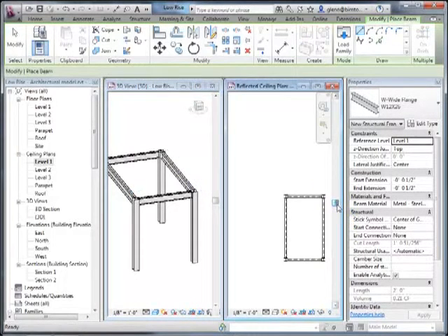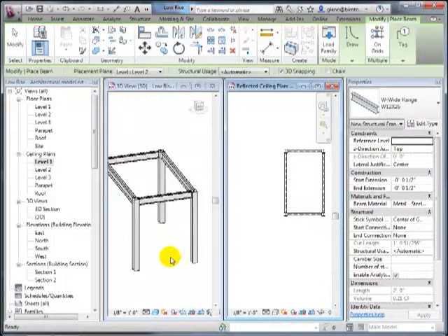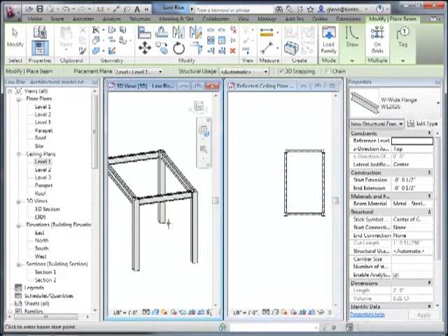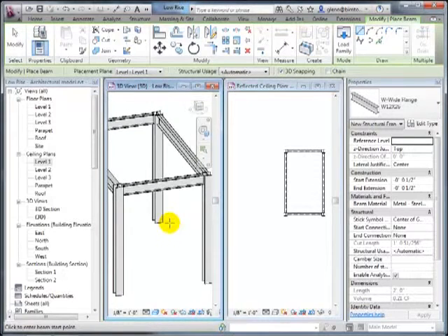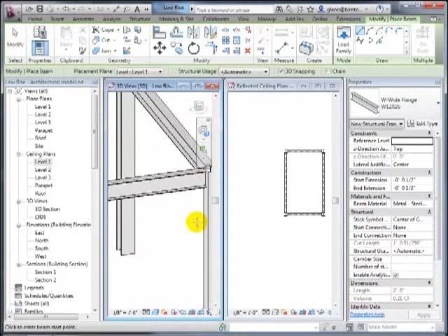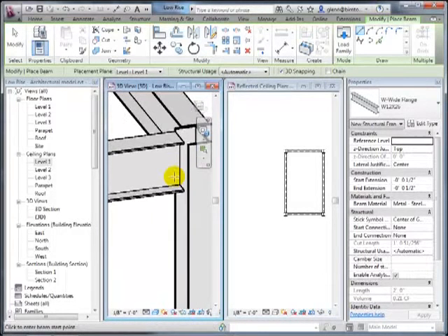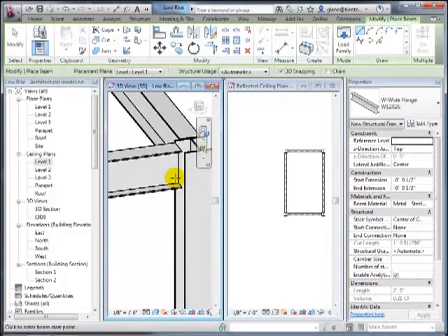So, noticing that you're snapping to the center of the column, but it's automatically resized. Do you have to snap to the center of the column? You do, because analytically, you want it to be to the center of the column. There's a whole separate discipline about how we detail the interface between this column and that beam. Right now, just graphically, it holds it off, and later we can go back and figure out whether it has a welded connection or some sort of haunch holding it up.